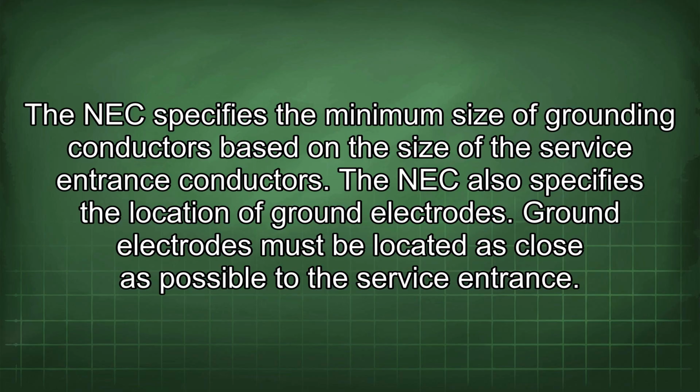The NEC specifies the minimum size of grounding conductors based on the size of the service entrance conductors. The NEC also specifies the location of ground electrodes. Ground electrodes must be located as close as possible to the service entrance.